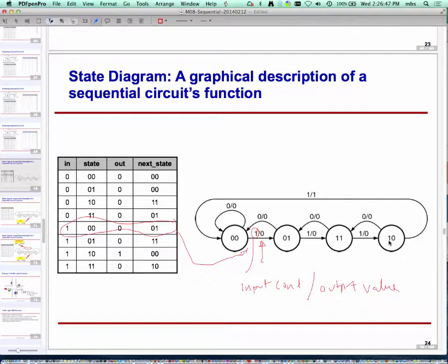That's how many nodes in my graph? 65,536 or something like that. So clearly, visual stuff is okay for simple things, but if you have lots of states, even this visual approach doesn't quite work out. And that's when you move to the next level of designing these state machines, which is essentially you write a piece of software.